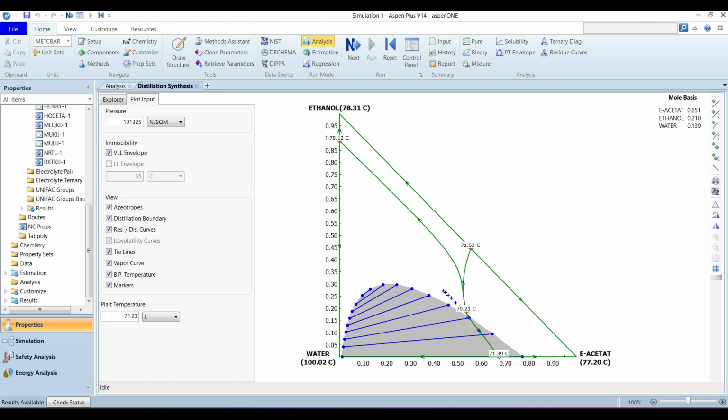So we have the same information of the liquid-liquid separation and the vapor-liquid separation on the same right angle triangle. To read, if we perform the distillation in any of the regions, what should be the distillate product composition and the reboiler product composition. For that purpose, you can use these tools. One of the tools is just add tie lines, the first two options. Then the next two options are add curves. These add curves are the residue curves, and the residue curves are for the distillation process.